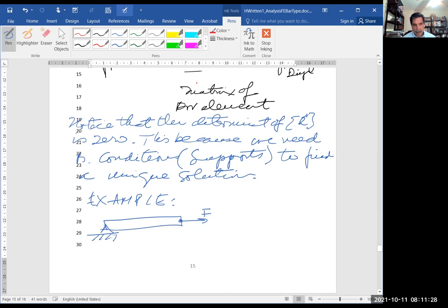Now, of course, we're going to discretize. It's easy. We're going to consider 1 and 2 joints, obviously, right? So this is the first element. There is only one, of course. We have EA. These are the properties of the section. So what can we say? We can say that according to this, the left end doesn't move. So immediately we can say that D1x is equal to 0.